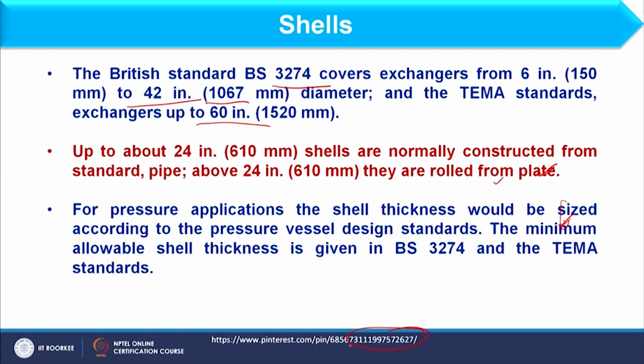So if the diameter is equal in both cases, pipe shell becomes cheaper in comparison to plate shell, because of the money involved in the rolling process, and that is an expensive process, right? So if a choice is available and your diameter is lying between both, that is pipe shell and plate shell, you should choose the pipe shell.